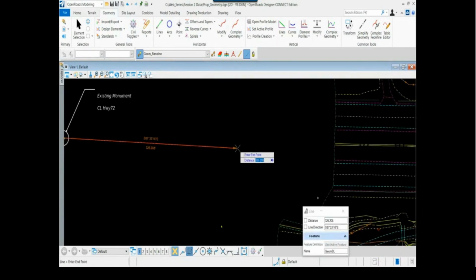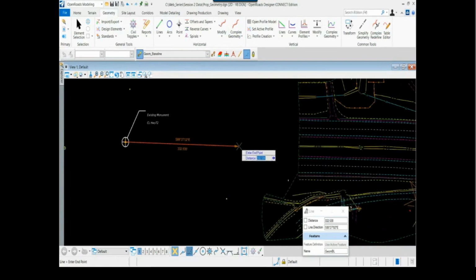And you'll notice as you draw that element, you've got heads-up prompts. You'll notice those on the cursor. And I'll try and explain those. On those heads-up prompts, number one, you can key into the highlighted field, as well as the arrows indicate that I can move between information, left or right. So I click the left arrow or the right arrow if I want to, and it tabs me through distance and direction that I can use to input data for this particular element.